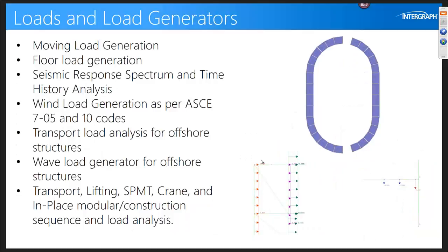A seismic response spectrum analysis can be done. If you wanted to do a time history analysis, you can do that as well. There's a wind load generator also in GT Strudel that can generate wind loads as per ASCE 7-05 code. You can use this product to design offshore structures and do wave loading on them.